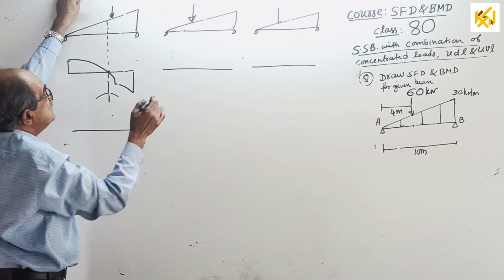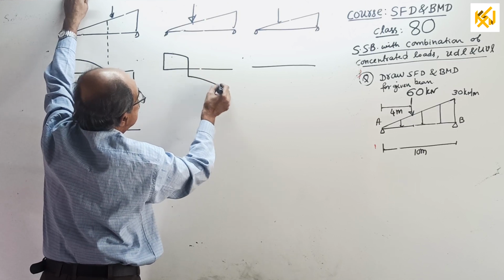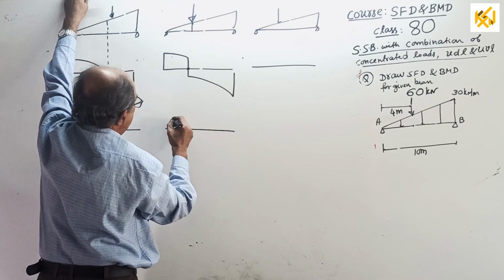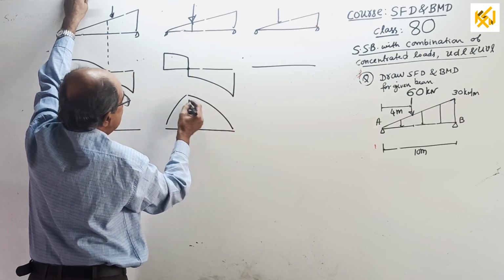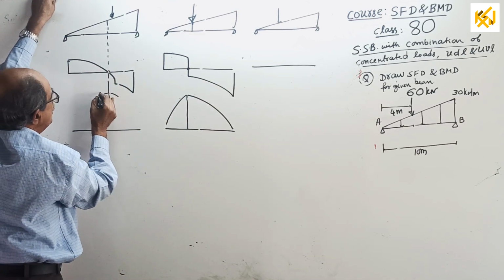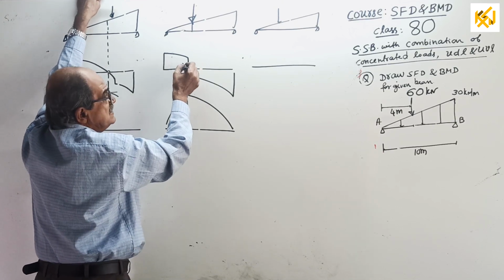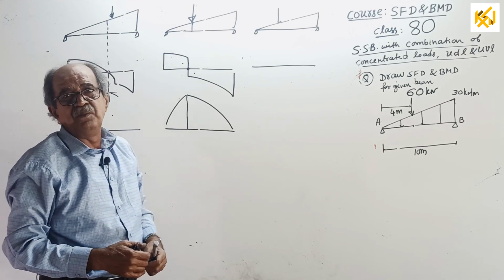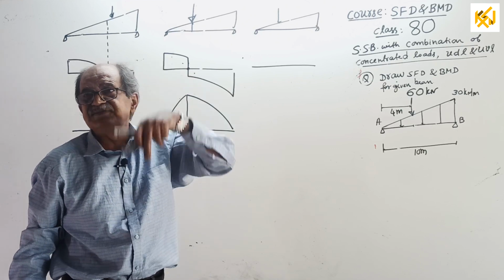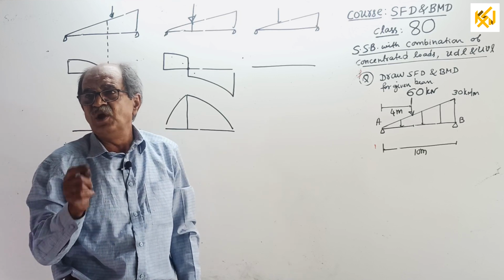Next, second question. You see the diagram. Your shear force diagram came this way. The shear force diagram crosses the baseline exactly at the point load. Here the BM will come this way and this way, with different slope either side. This is the maximum value. But at the maximum BM here, the slope is not 0 because either side shear force is there, since this maximum BM is at the point where the SFD suddenly changes sign. If it suddenly changes sign, then the slope will not be 0. Only if it is perfectly 0 shear force will the slope be 0.